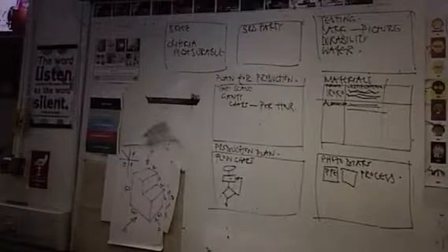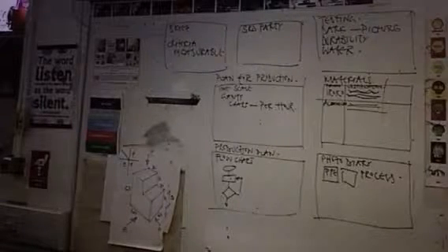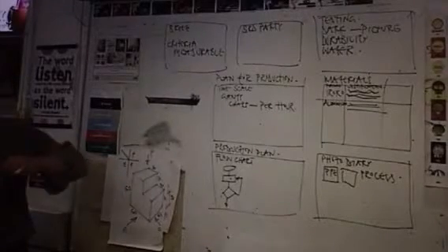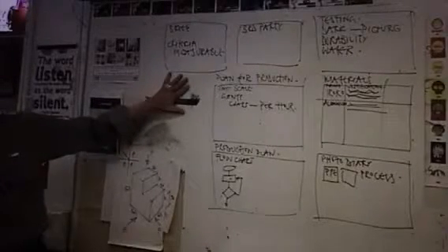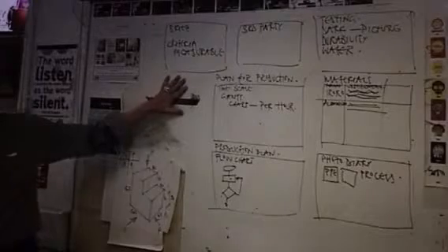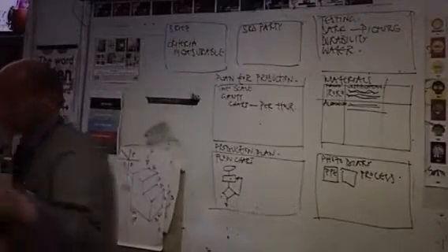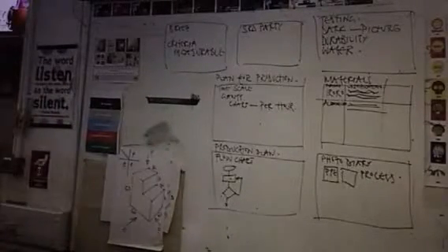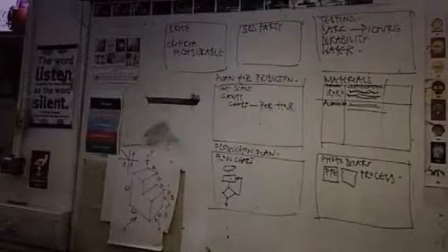Next. Testing, recording or documenting range of tests, user group, measure against orthographic and check against criteria. Okay, so that's actually another test that we didn't talk about. You could check back at your orthographic drawing, the one that I give you. You could show pictures of this with a vernier or a ruler against it, and that would be testing the dimensions of the product you made against your original intention, which was the orthographic drawing.